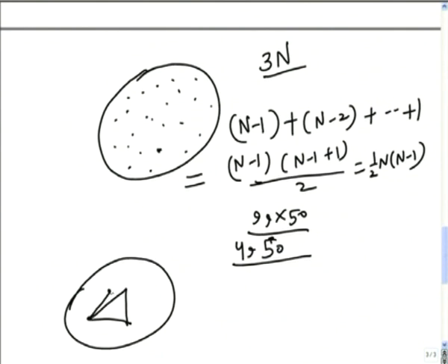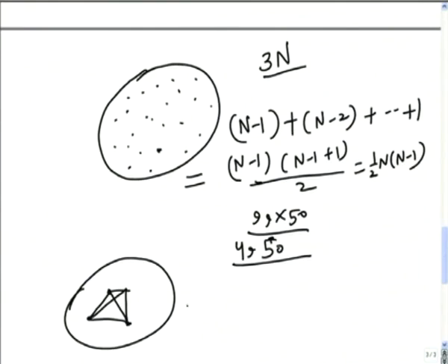So once you have fixed 3 points on the body, all other points get constrained, they cannot have their independent degrees of freedom. So we can only take 3 reference points, but the 3 reference points themselves are also not independent. There are 3 equations of distance actually. Thus the independent degrees of freedom are 3 into 3, 9 minus 3, that means 6.